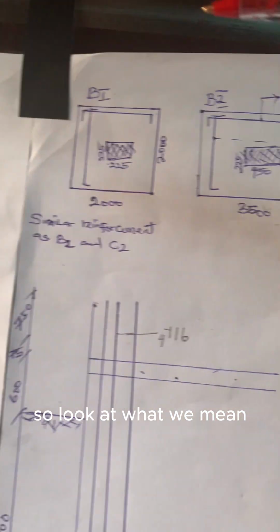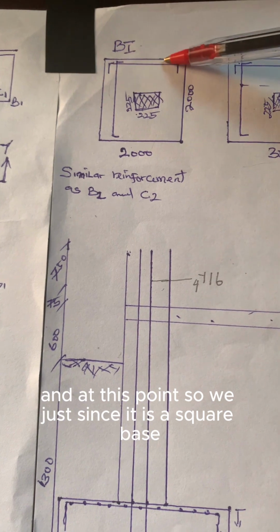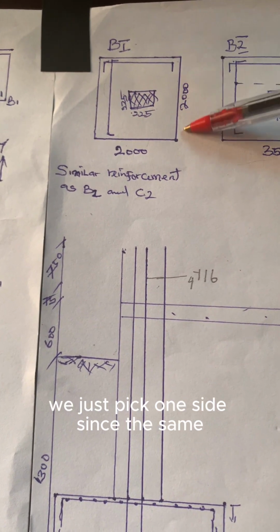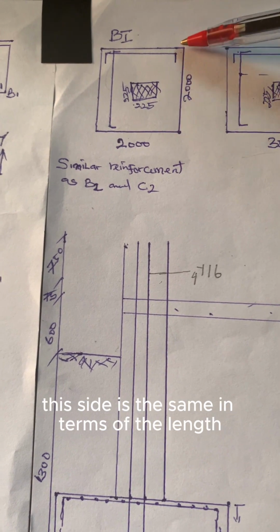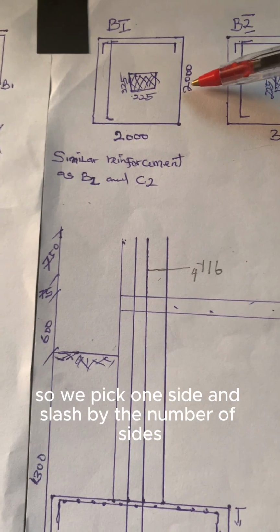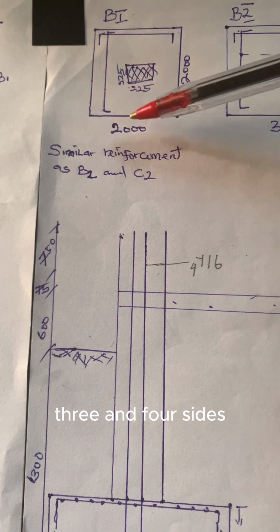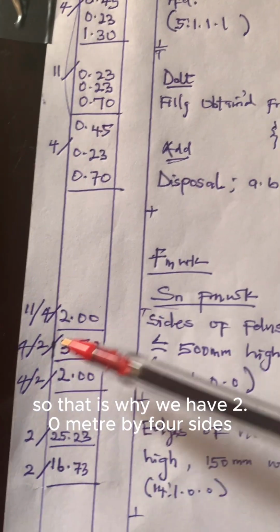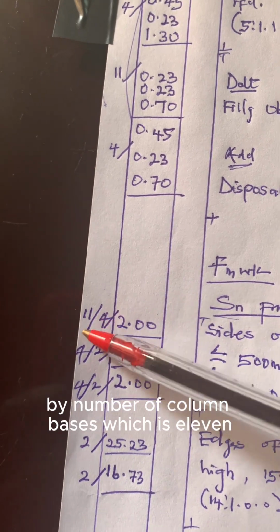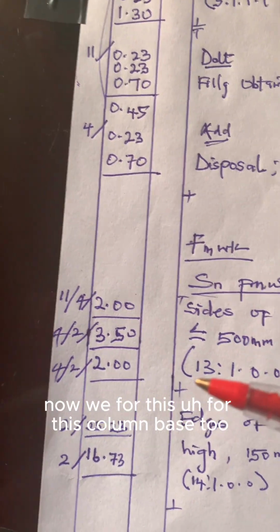So look at what we mean. We need to place formwork here at this point and at this point. Since it is a square base, we just pick one side, since this side is the same in terms of length as the other remaining 3. So we pick one side and slash by the number of sides, which is 1, 2, 3, and 4 sides. So that is why we have 2.0 meter by 4 sides by number of column bases, which is 11.